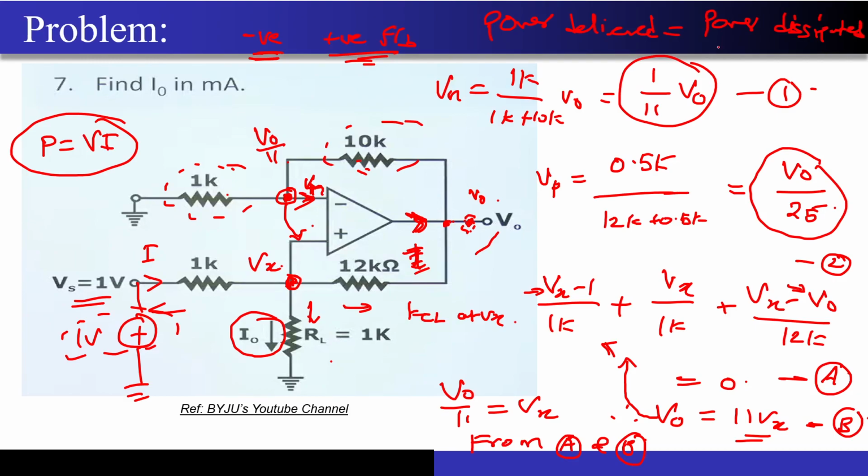A follow-up question for that. For example, if you consider the 1K that is connected at the positive terminal, let's assume there's a voltage connected. We get a voltage there due to the input 1 volt, right? Because of that 1 volt, there is a current flowing through RL and the other 1 kilo ohm. So now there is some power dissipated there because of the input voltage source also, right? Yeah, correct.